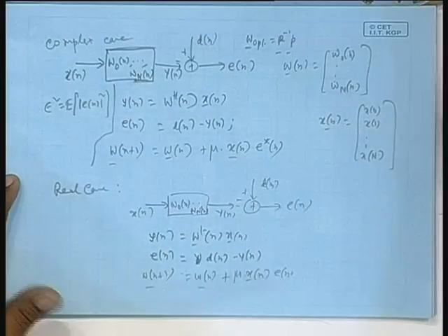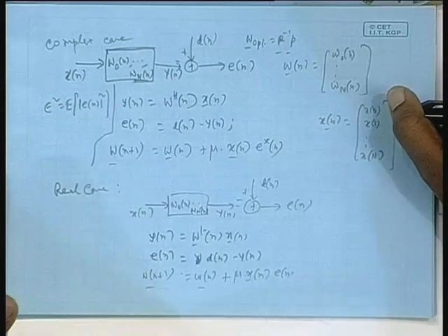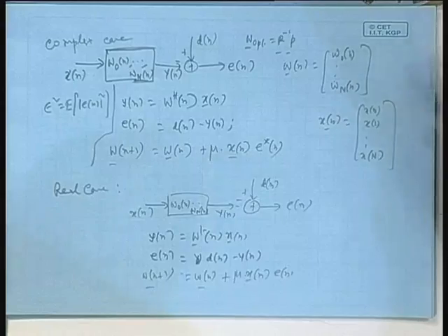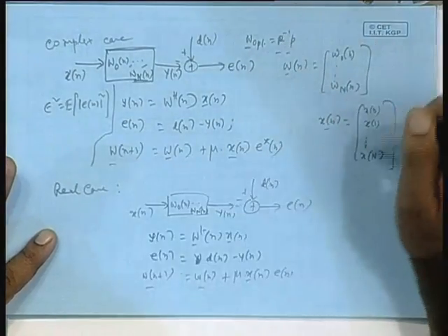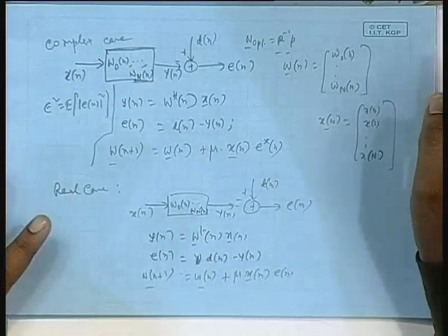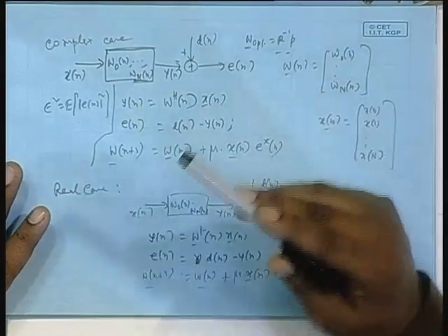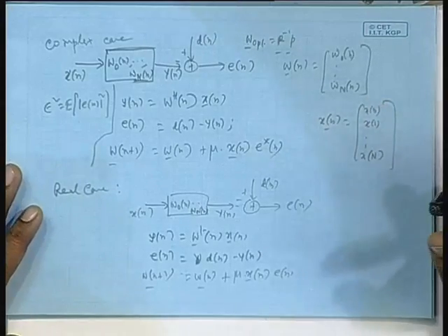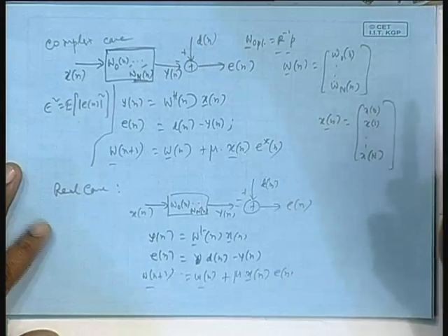You remember how we obtained this algorithm? We first started with the steepest descent, which was an offline procedure. Okay, the iterative offline procedure. We took that plot of epsilon square versus all the tap weights. That was a quadratic function, it has a unique minima. So, we started with one point and then went in the opposite direction of the gradient, multiplying the gradient value with some suitable constant, step size mu, and then went back and forth around that optima point, and then finally converged on that.